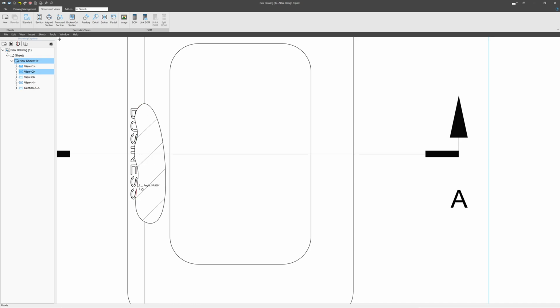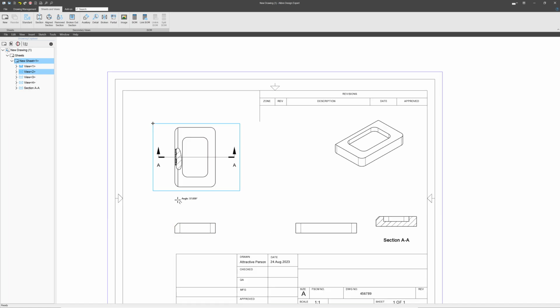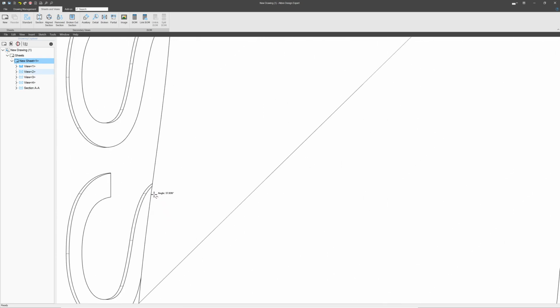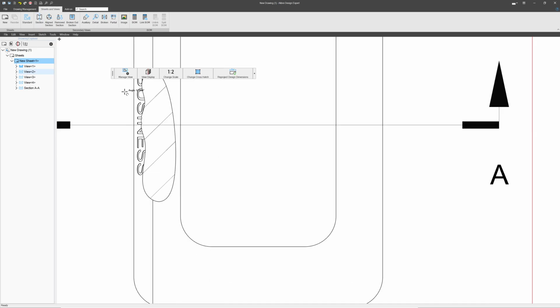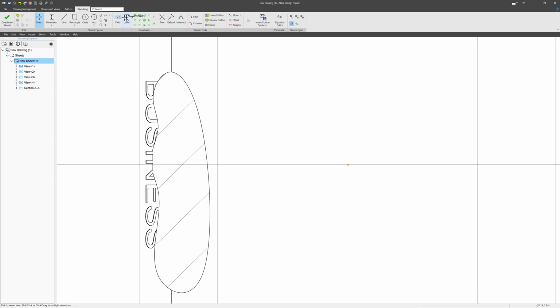We may want to highlight something about this view, but as you can see, if I zoom out and look at the whole drawing, those are really small details. How do I make these details bigger? Well, for that, I have several options, but I think my best option is going to be creating another sketch. So we go to Drawing Management, activate Sketch. I'll draw an ellipse around the areas that I really wish to highlight a lot. And I'll move the ellipse up just a little bit.